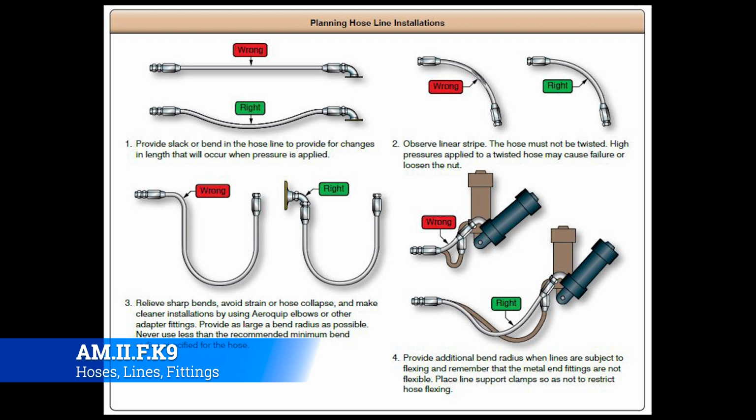Now the same thing goes for the one just below that, in the bottom left-hand corner. Those sharp bends, effectively, it's like banjoing a line. You need to make sure that you're inside the allowable bend radius for your flex lines, because if you just do a hard 90 like that, then effectively in that 90 you have banjoed that line.